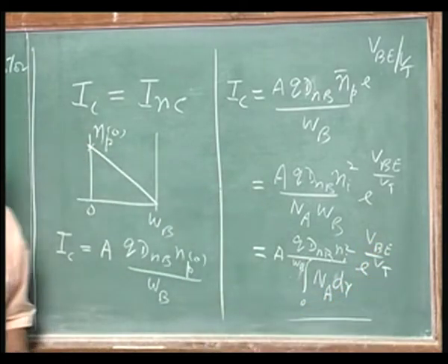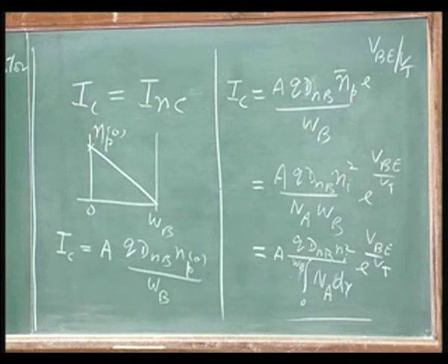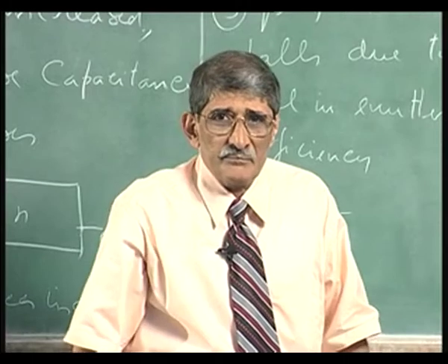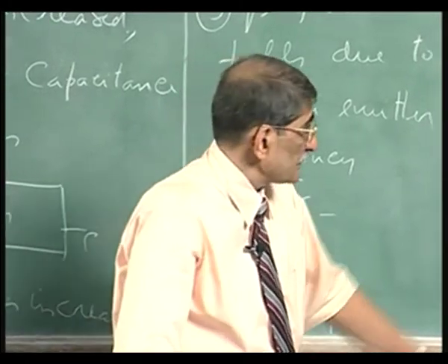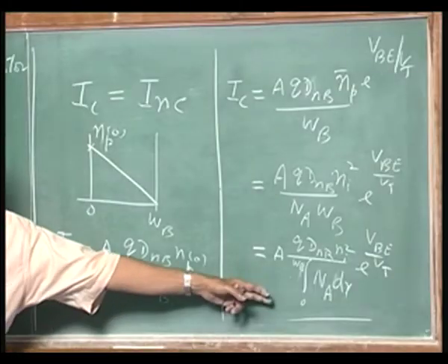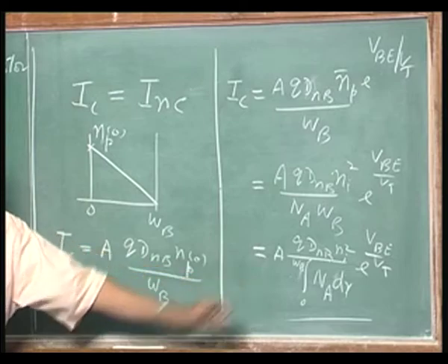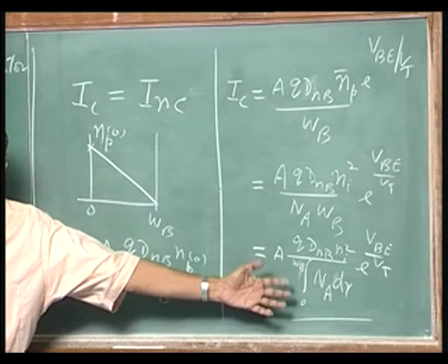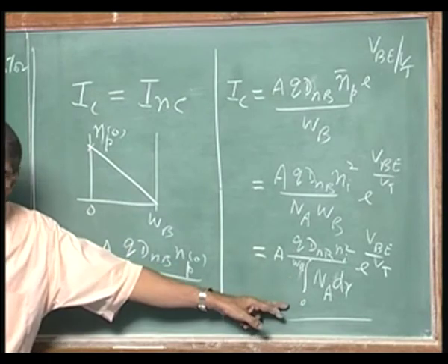Okay, this is just to remind you, we all know it. I just reproduced whatever we have been discussing earlier in many of the lectures. You must have heard about these things. This is the total integrated doping. I can call it NA total in the base, the denominator.